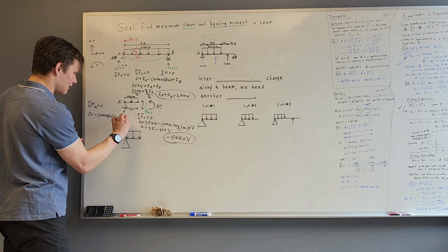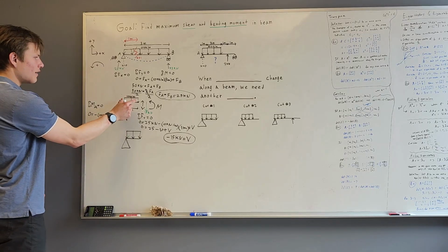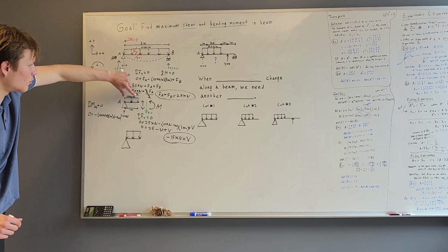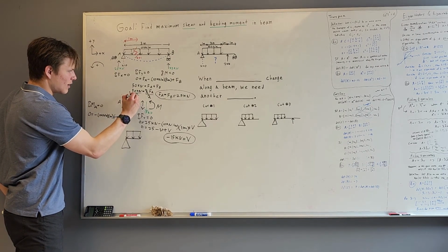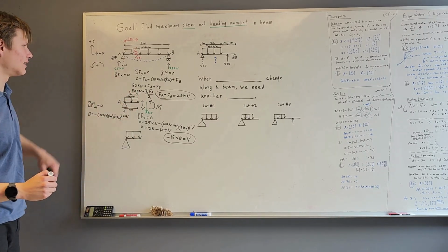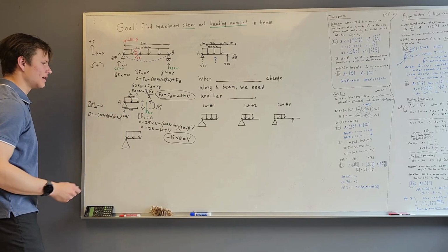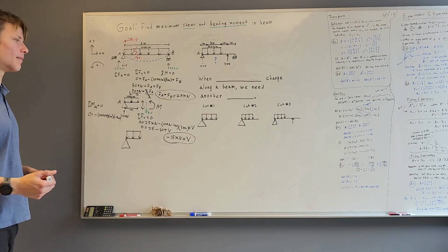And why is it 0.5 meters? Well, that's because the equivalent point load, if we were to transfer this UDL into an equivalent force, would act right through the middle of that UDL. And the middle is half of this distance right here. It's half of 1 meter. We have 0.5 meters as our moment arm.